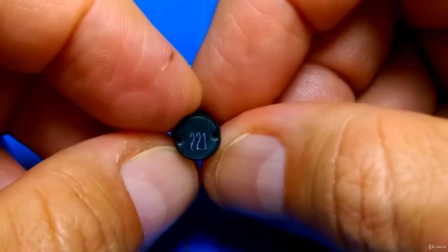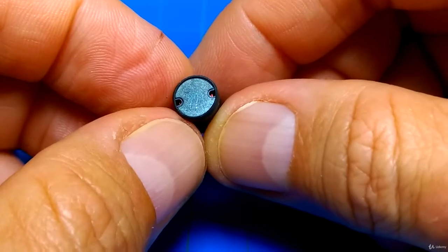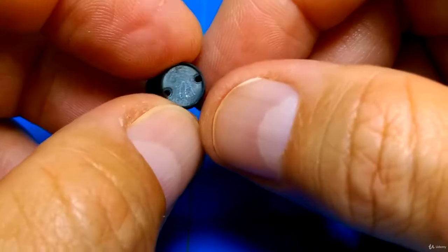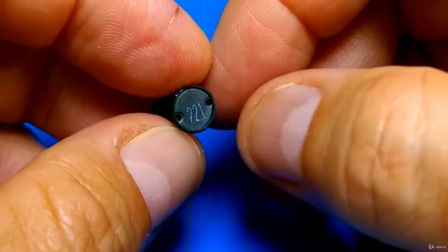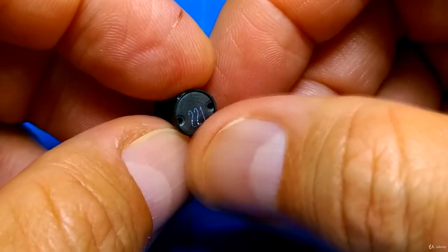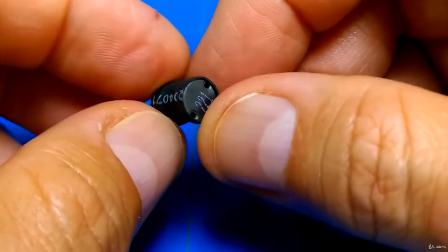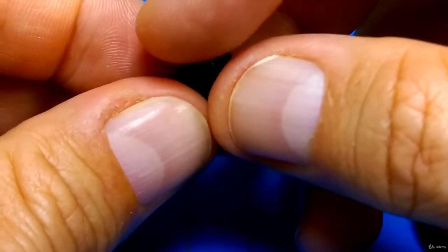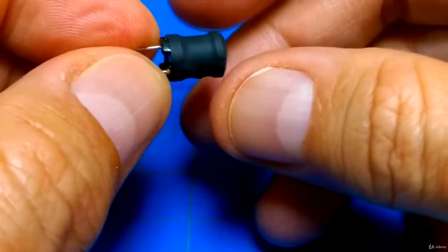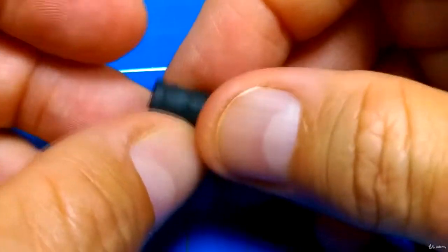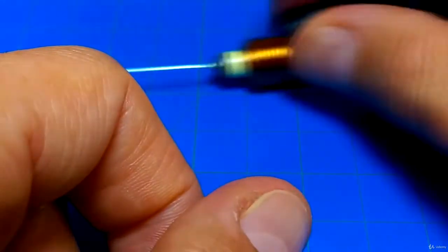All right, and then if you read this, these things have all kinds of different encodings, but this one is probably 2 something, right? What this means in this case is the first two digits are 2, and then this is 10 to the 1, or times 10. So this is 220 microhenries, I believe. Not 22 microhenries, I believe it's 220 microhenries. Again, if you forget how to read them or you haven't played with them in a while, you just get your meter out, if you have an inductance meter, and then you just measure it, okay? But the values are on there some way, and sometimes there's no value on there, all right?